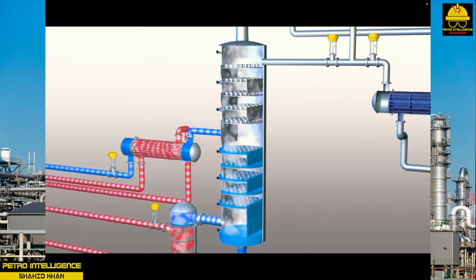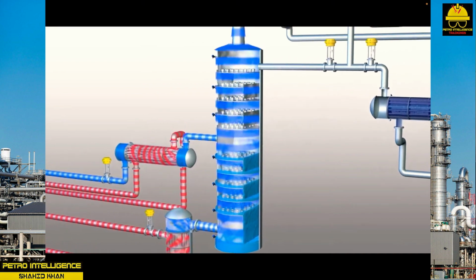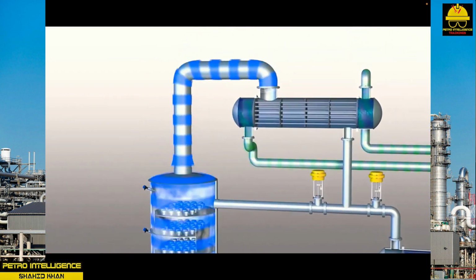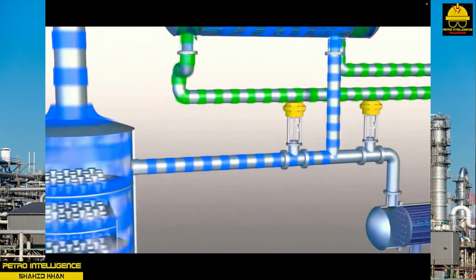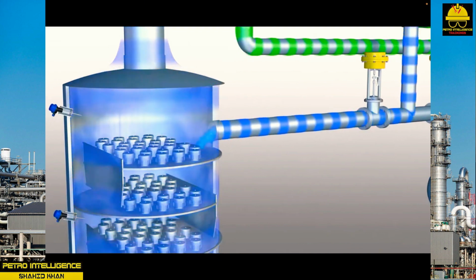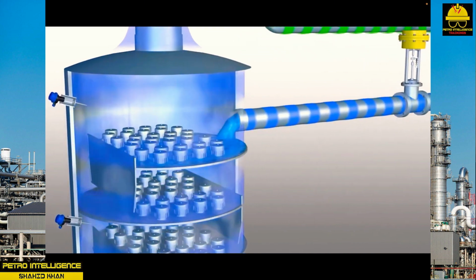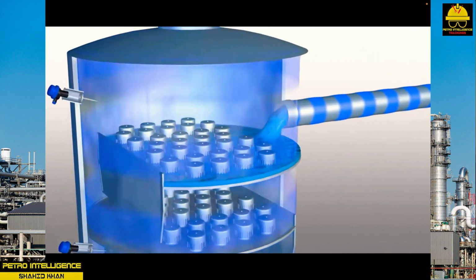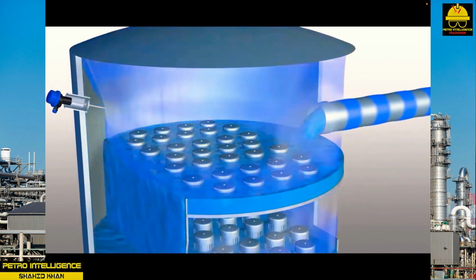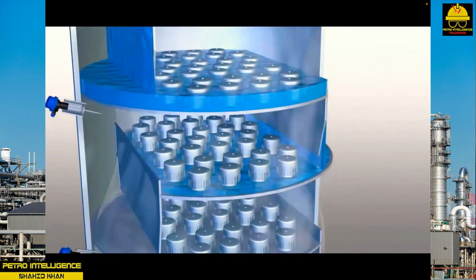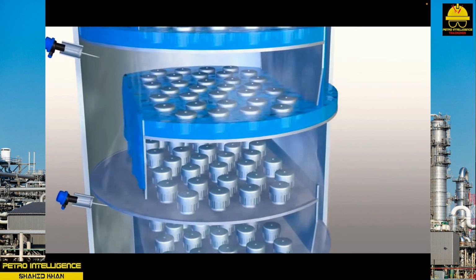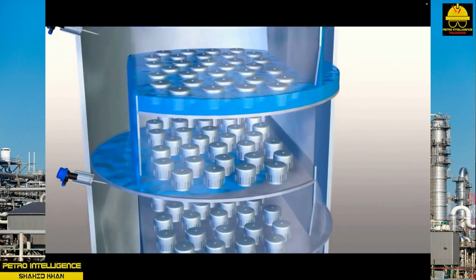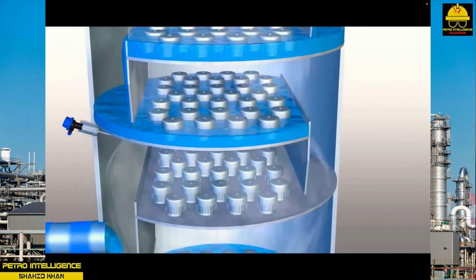distillate. The bottom system is composed of a section in the column designed to allow liquids to boil and roll freely. A reboiler is connected to this section to maintain and add heat energy into the liquid. The term reboil indicates that the liquid was originally boiling. Hot vapors are returned from the reboiler to the bottom of the column below the bottom tray.